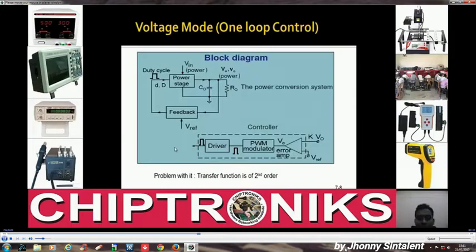In voltage mode control, what happens is the output voltage is fed back to the input to check the error. And we have a V reference. Like we already know that a 3.3 volt regulator has to generate 3.3 volts. We already know a reference. So if there is any difference in the output, say the notebook motherboard requires more current, then the voltage would get dropped, right? But we have to fix this voltage, so the error will get fed back to the input, and that would change the PWM.